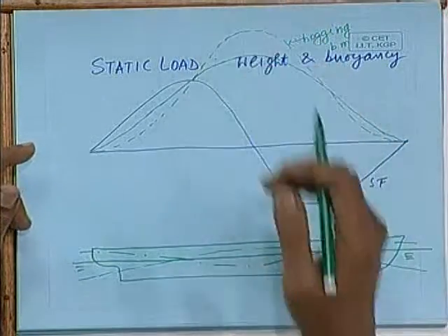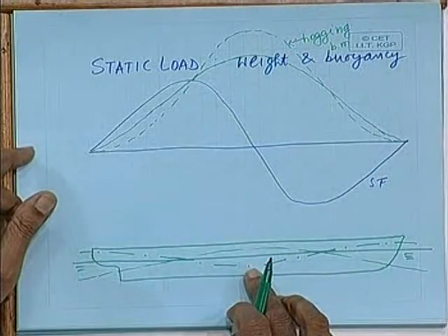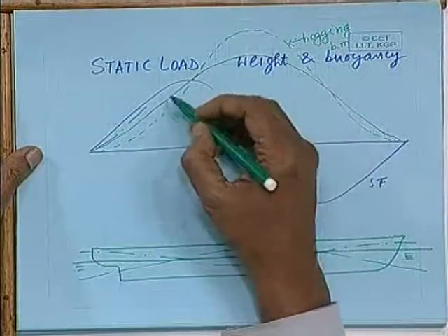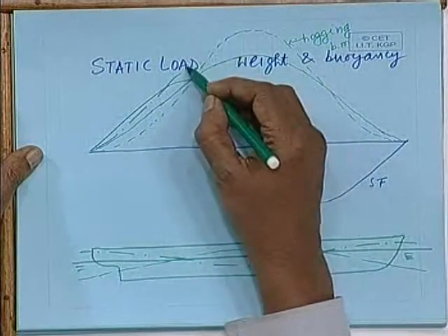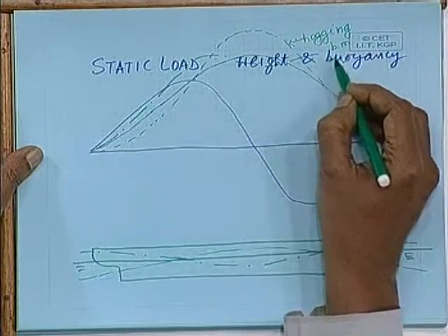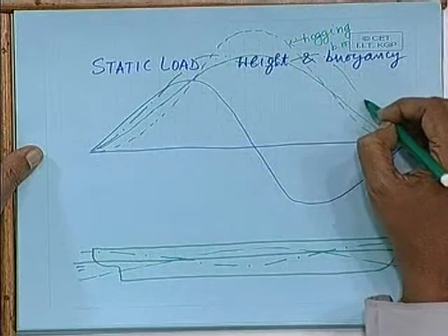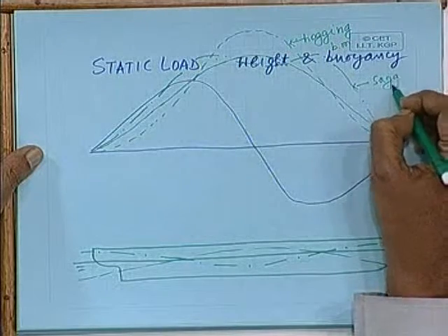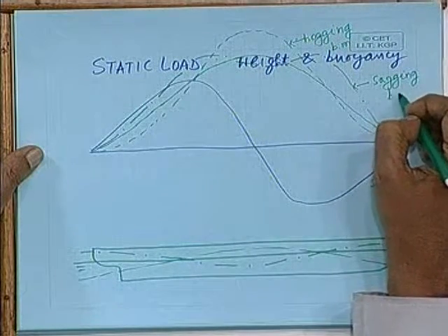The bending moment in the middle will reduce because the buoyancy has come down drastically, and towards the ends it will increase, towards the places away from midship it will maximize itself. So, maybe typically it may look like this. This is normally called the sagging bending moment.